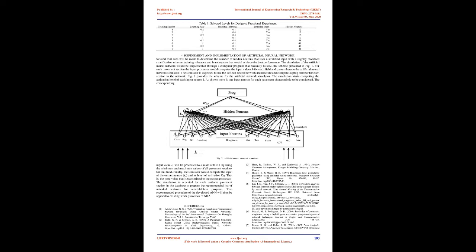Once the database is created, the average pavement condition and traffic at the time that the road sections are programmed will be compiled for each road section in the database. In addition, cracking and roughness 1, 2, and 3 years before the programming year, the year when the sections were selected, and the average maintenance cost for the last 3 years will be computed.